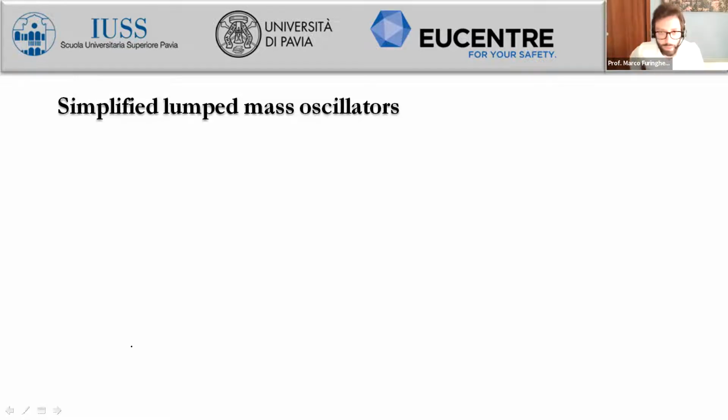And for what we have seen, our isolation systems are highly nonlinear, especially lead rubber bearings and curved surface sliders. Also for rubber bearings there is a little bit of hysteresis, which can be modeled through a linear dashpot. There will be a very small hysteresis. This is why they are directly associated to very low values of damping ratios. But then we know, as we have seen yesterday also in SAP 2000, that we also have to model the hysteretic response of frictional devices, and that is actually highly nonlinear.